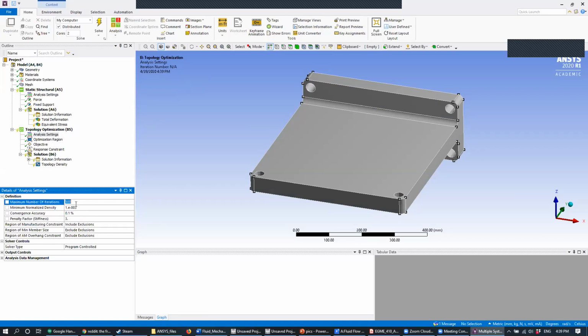Because in theory, with the guess and check approach, and not really knowing what the absolute best solution is, you could guess and check for an infinite amount of time, until you just grow tired of it. But a lot of times we don't have time to let the computer guess and check until it's satisfied. So we need to put a cap on how many iterations it can run. Here the default number is 500. For now that's okay, just because this model was relatively cheap. We only had about 7,000 elements here.